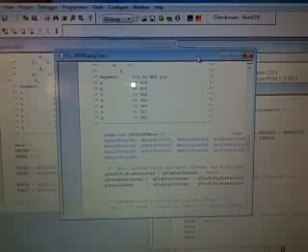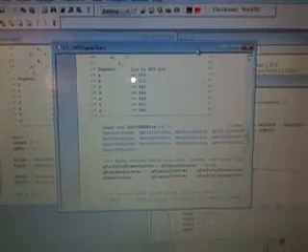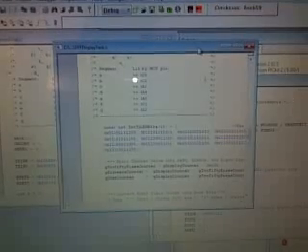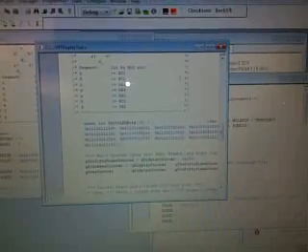The next program was FFF-display-test.c, which uses those 3 displays to count from 0 to FFF in hex and display the hexadecimal characters appropriately. This proves that my bit mapping for those hex characters and the algorithm used to split the big number into little numbers for each individual display works.